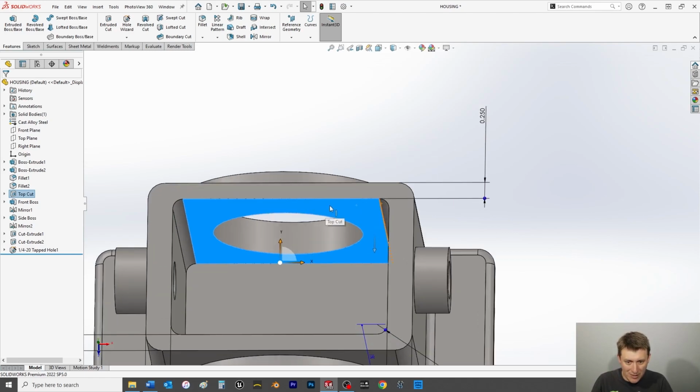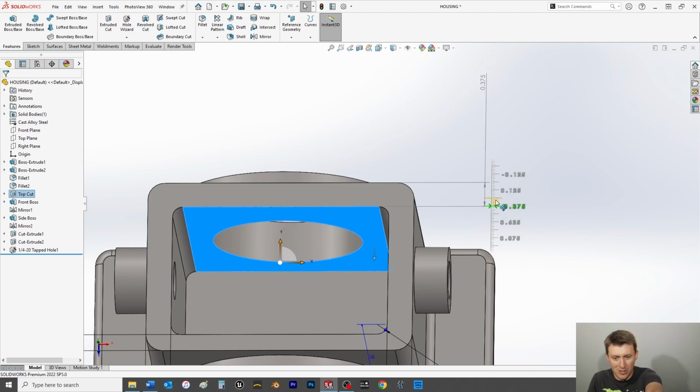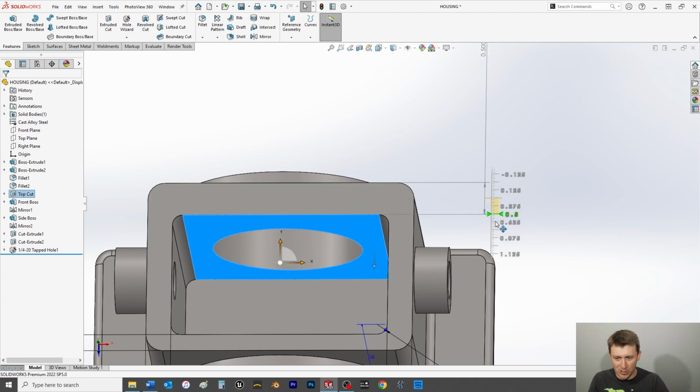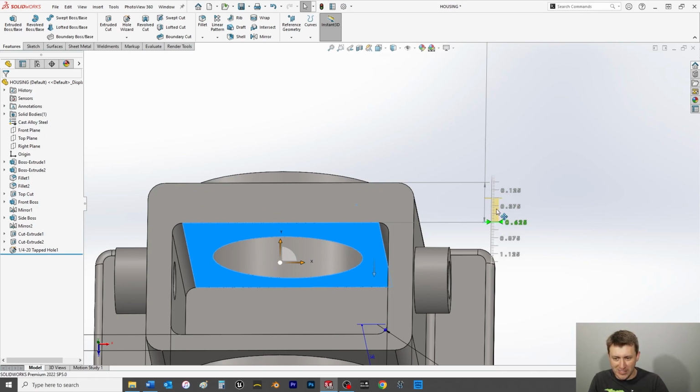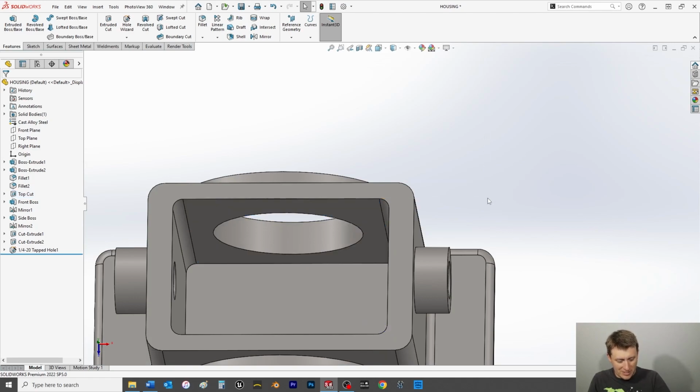So now that we have changed it, I'll do it again, showing this wall thickness. Hover over the blue ball, click, drag to the right, and notice how the wall thickness is changing. Super thick. Nice. But we want this at 0.25. And then I'll hit escape, Control S, and now we will move on to page 87, section 2.5.